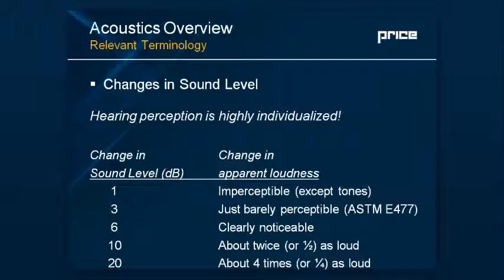It's worth pointing this out because sometimes you're going to get a schedule or see requirements in the specification, and it's very easy when you're doing a review to say, okay, you're off by a single dB, so I'm going to fail you, or you're going to have to resubmit. But in many cases, this might not be the biggest issue, so it's worth talking with the consultant or the manufacturer to really understand whether this is a cause for concern or not.